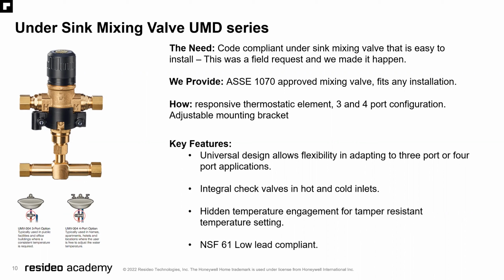Responsive thermostatic element in a 3 or 4 port configuration. That little T on the bottom unscrews, and you can mount it in the 3-port option, or you can leave it there and then you have a 4-port option. Has the integral check valves in the hot and cold inlets. Hidden temperature engagement for tamper-resistant temperature, because this is of course expected to be point of service. And it is NSF 61 low lead compliant.